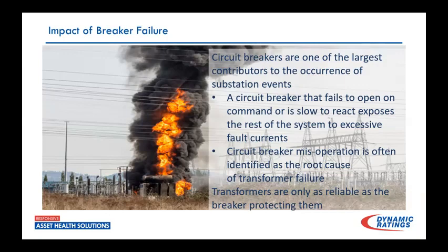We also had several failures that were just due to breakers that did not operate. Now that can be related some to your relay scheme. The 2 instances I'm thinking of, there were no breaker fails in place. Kind of remote stations, fault currents just didn't make it back to kill the line at the station before, and something as simple as something getting on that bus and that high side not being able to come open. We saw 6 minutes of through fault on one of the events, failed the low side breaker.